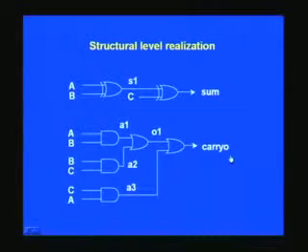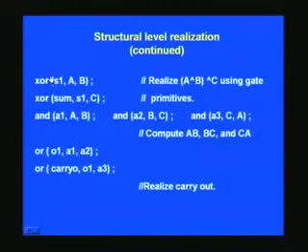And in the next slide you see the gate level implementation for the same, and notice that you may have to go for say 3, 5, 7 lines here, and this is very close, akin to your standard schematic based entry, right. So here, what you see is that the intermediate signal, this is to invoke a primitive which is available in the libraries of Verilog. This is exclusive OR which you are already familiar with, and similarly this is AND and OR, and the first one stands for the output of that gate, whereas the rest will be the inputs. As I mentioned, they are all normally restricted to 2 inputs, and some offer higher inputs as well, but that's not guaranteed on all platforms.